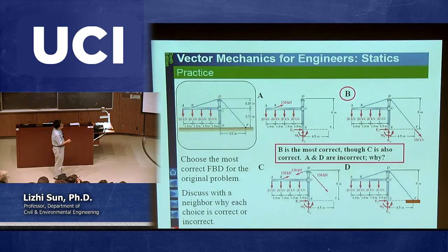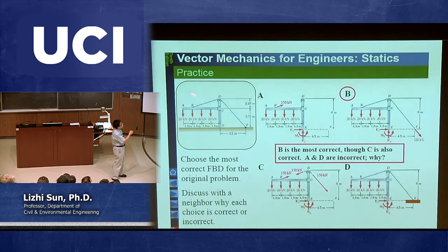So this is the example I talk about in terms of cables. There's multiple ways you can cut, but no matter what, after you cut, you need to plot those forces correctly. I'm not saying you cannot cut here. You can cut here, it's not a problem, but you need to give forces appropriately. So that's why this is correct. Just in case you want to cut here, no problem.